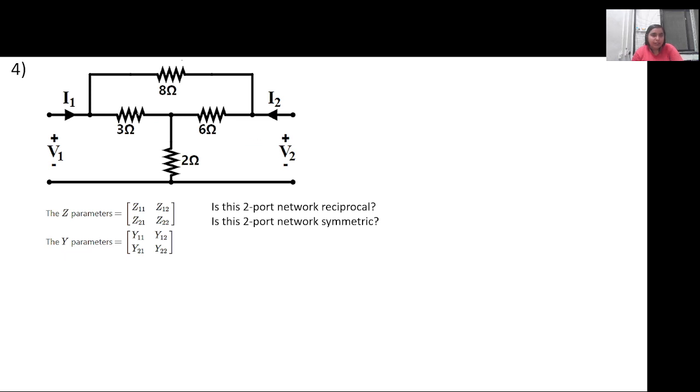If you see, in this case, writing the equations for each of the branches, there will be multiple KCL equations in these three nodes, or if you are to write KVL, there will be 3 loops for it, and solving it will be a little bit difficult. So what can we do? I hope you have seen the sir's lecture where sir denotes this T kind of network, this star kind of network, and converts it into a delta network. So this star network can be converted to an equivalent delta network, right?